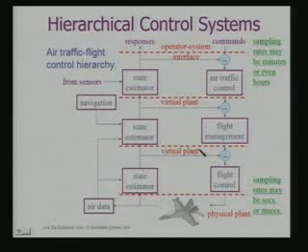You basically take the various inputs to a state estimator, and on the basis of that you decide upon the control action. So each of these control layers or control actions has to be executed at multiple time periods. The timing constraints are multiple because all of them need to satisfy your sampling intervals, and they are hierarchical and not independent because one is based upon the other, okay. So in this case also we have got a multi-rate but hierarchical system.